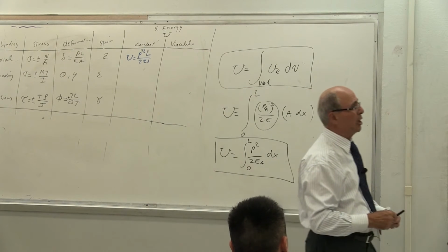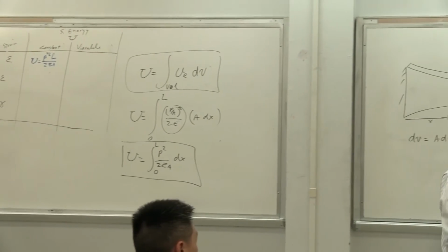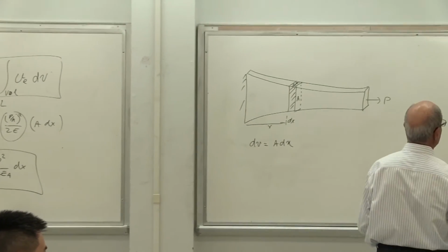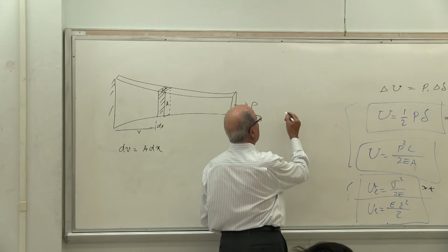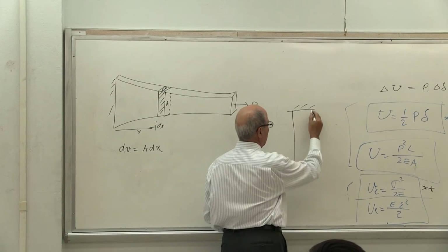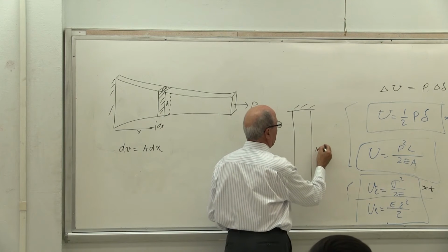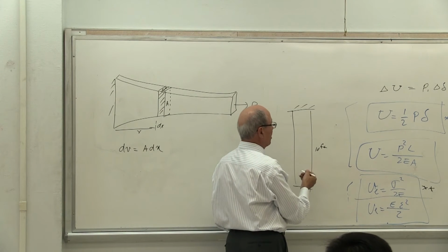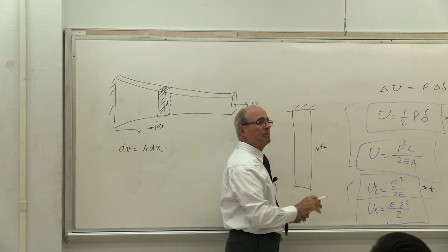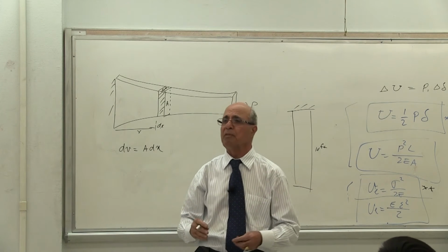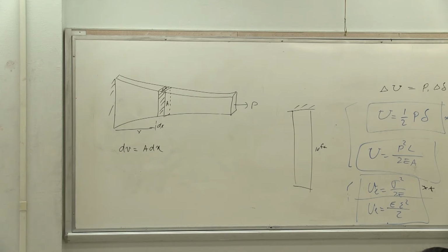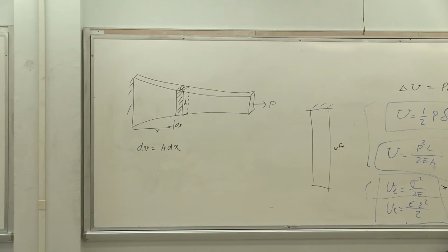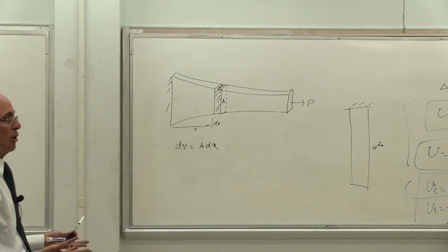Also for the other class, I mentioned the problem that P is variable, which we have never mentioned, but we should have mentioned it. But we avoid all the mathematical problems, right? If I have a rod here, and it is, let's say, 10 foot long, and it has a cross section, and let's say each foot of this is made of material which weighs about 50 pounds per foot, then what P do I have there? Is it going to be stretched because of its weight? Yes. So how do I represent them?